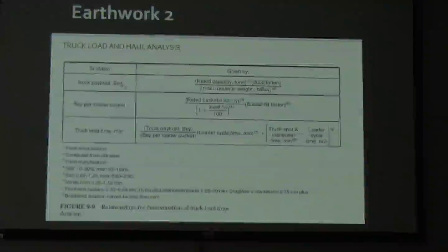Again, here's our analysis using our shrinkage factor and the volume of the bucket size, the truck payloads in bank cubic yards, and then the truck load time, the amount of time it takes to actually load the truck, using the spot time on the truck. So this is the relationship for determining truck load time. How much material, how many buckets do we need to fill it, and then the time for that loader to reach its cycle time.